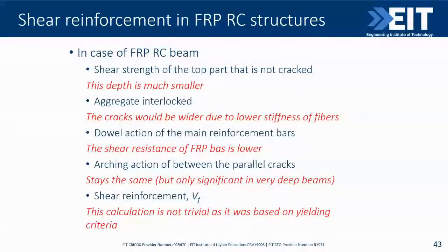However, what are the differences when we look at the FRP RC beam? The shear strength of the top part is not the first one. In practice, the differences again: the depth of the neutral axis, like we said, and the compressive part of the concrete is much less, so the contribution of this will be insignificant.